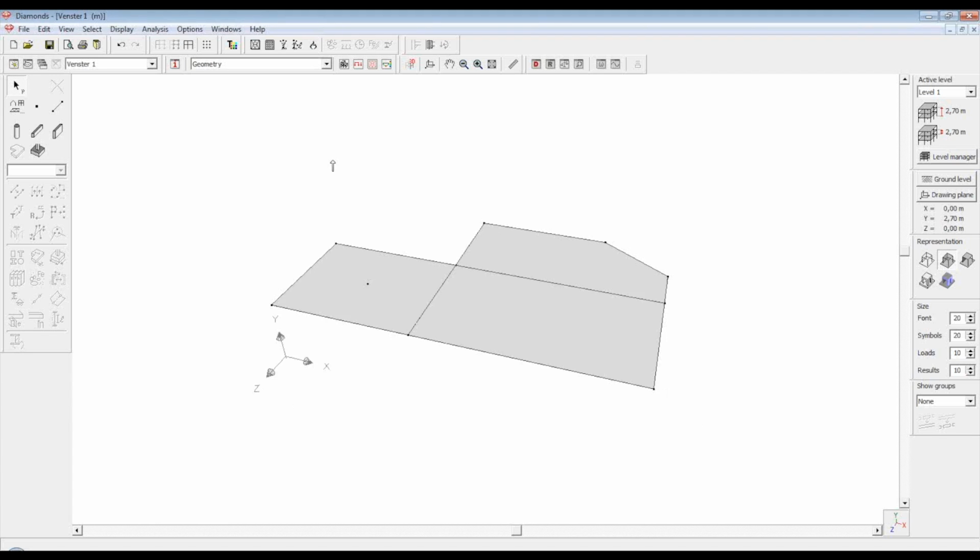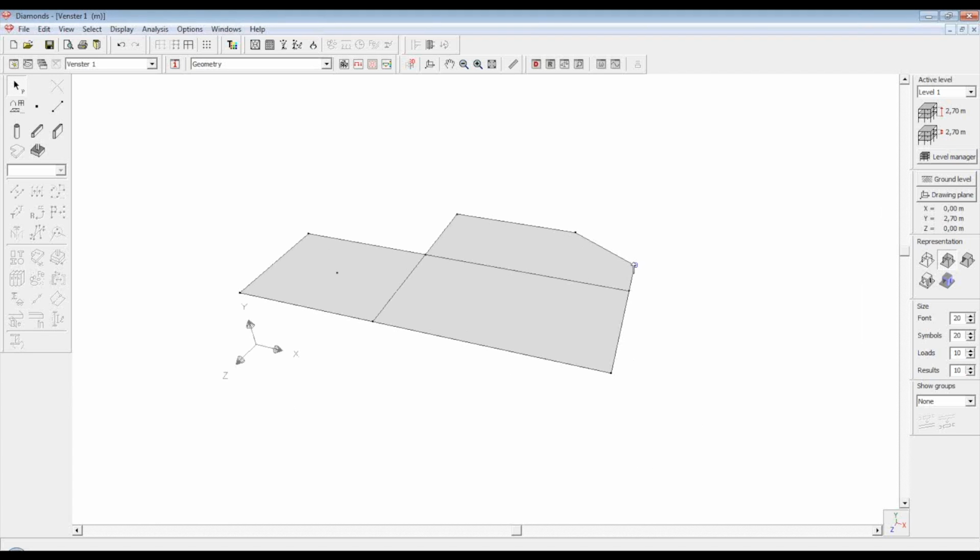In a 3D view, you can also draw lines, but only between existing nodes or using the intelligent cursor, meaning the parallel lines, the orthogonal junction, or the middle halfway junction possibility. This is again, of course, with the create line function. Another option, instead of just creating empty lines, is drawing beams, columns, and walls directly on the screen. Let us start with beams.